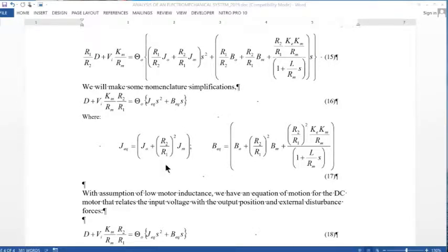And here's an important piece of it. Whatever the output inertia is on that output gear, that's whatever I measure. The input inertia, the inertia that I see from the motor, is reflected to the output space by the gear ratio, but the gear ratio is squared. And oftentimes you put a very big gear ratio in. So when you do, you really increase the effective inertia of your armature.